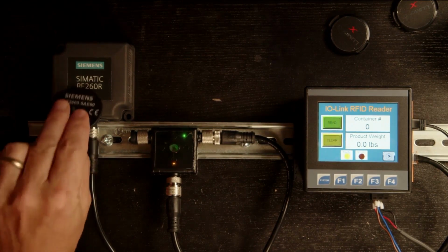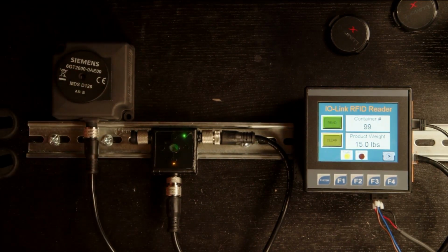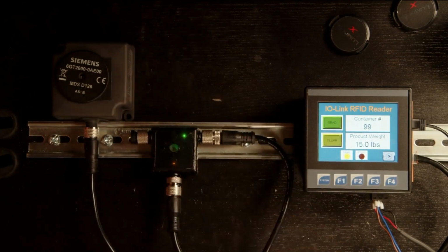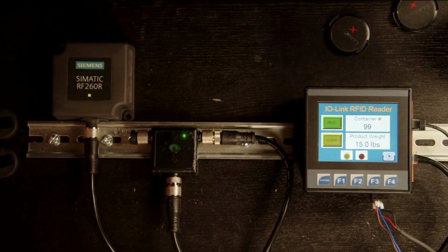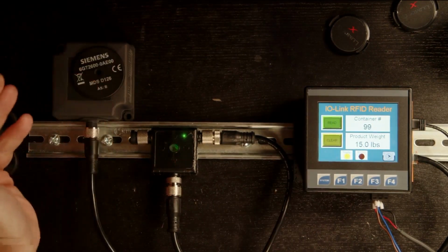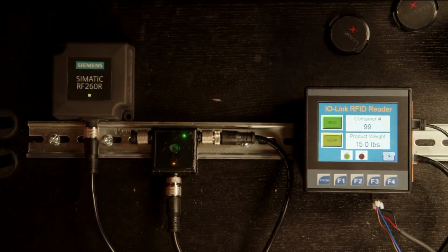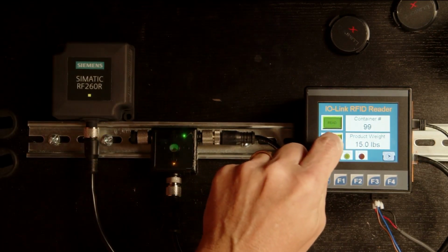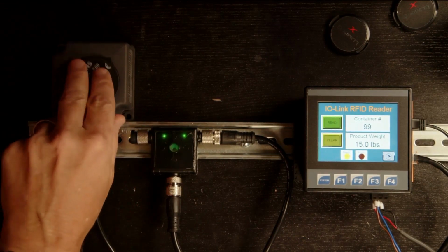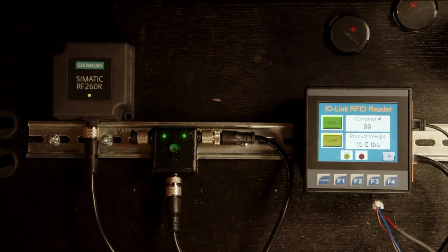And again, next time my tag comes across, okay, I get the data there, my ready bit turned on. I can then store that data away, clear the data away, and get ready for the next tag. Don't want to forget to arm it. There we go. Repeat the process. Store the data away, clear it, rearm the reader, and away we go. So very straightforward to read tags using the interface.